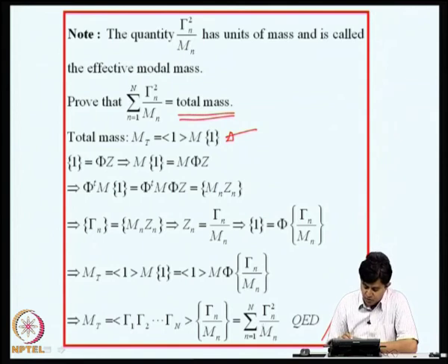Now, this, I said, is useful in modeling because one of the questions that we need to consider is how many modes we should include in analyzing a multi-degree of freedom system. So, a rule that we can adopt is we should include as many modes as is required to capture say 90% of the mass of the structure. So, you can go on evaluating the effective modal mass and you can retain as many modes as is needed to capture about 90% of the mass of the structure. So, that can be one of the criteria.